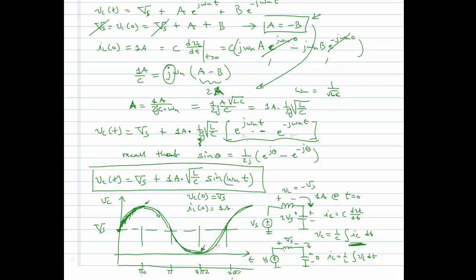And as that current starts increasing, it will again deposit charge onto the capacitor, causing the capacitor voltage to go back up. Alright, so at this point, what have we accomplished? We have ground through the math to solve our first second-order differential equation, or second-order circuit. But we have constrained ourselves to an LC circuit. We have not yet looked at an RLC circuit.